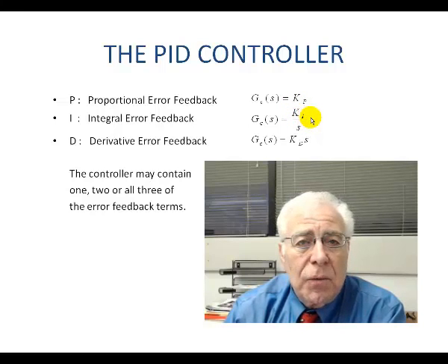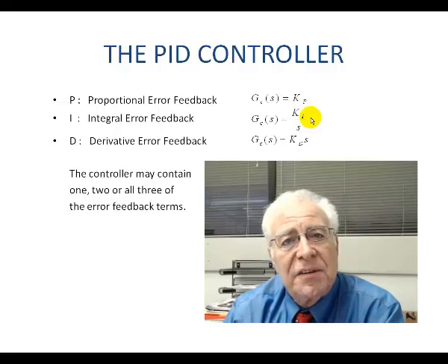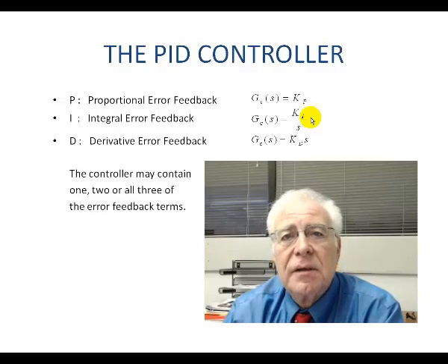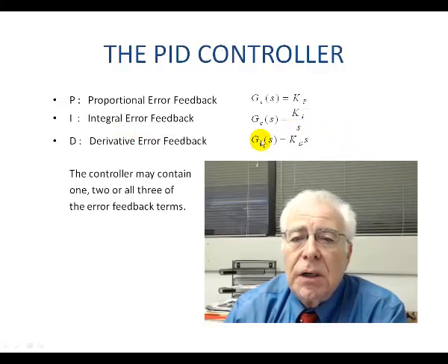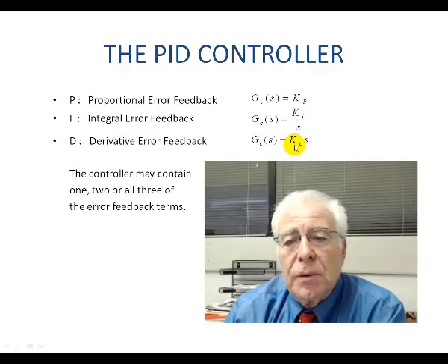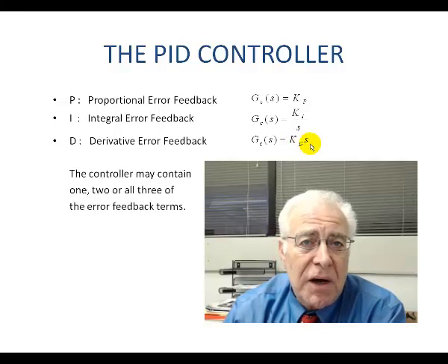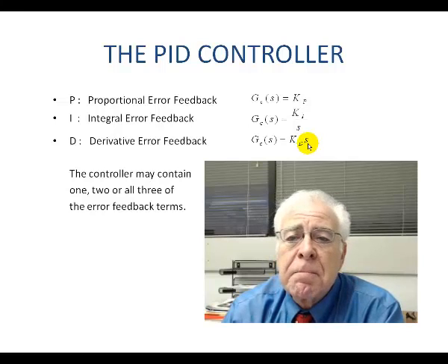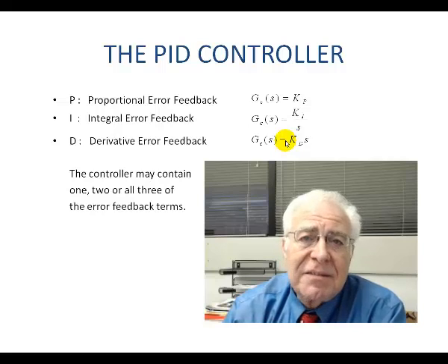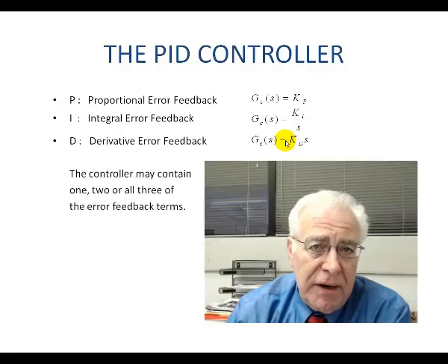And since 1 over S is the Laplace operator for integration, this integrates the error and feeds that back. Similarly, G sub C equal to Kd times S, since S is the derivative operator in the Laplace space. Kd times S feeds back a derivative of the error.